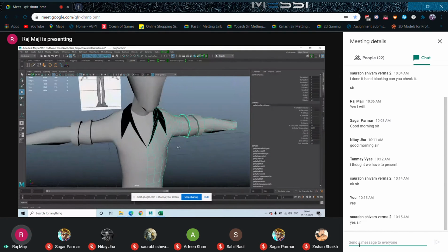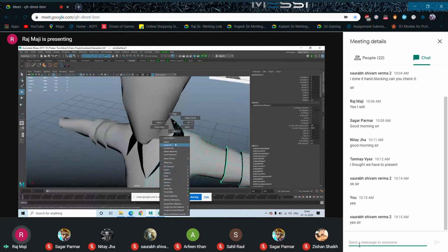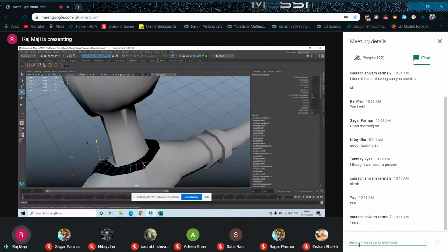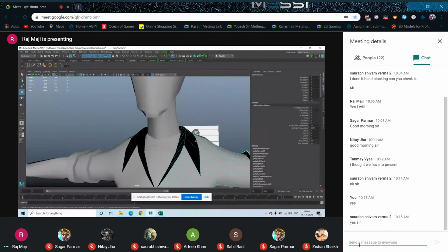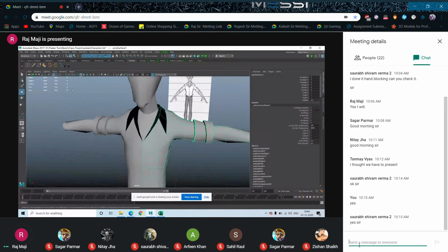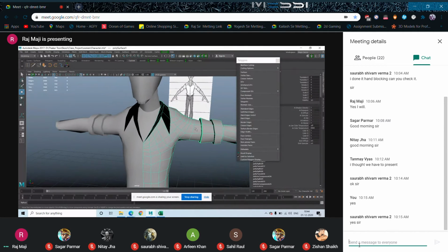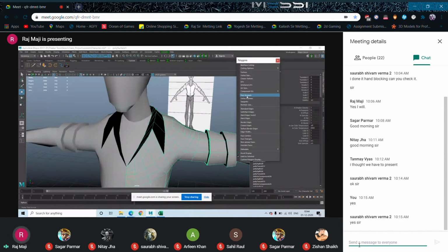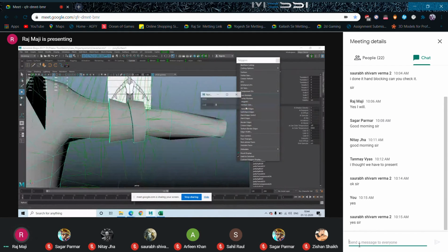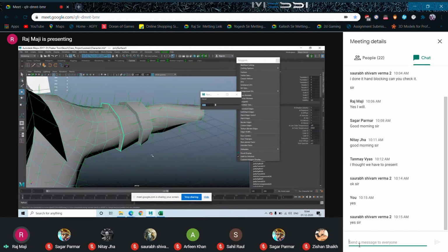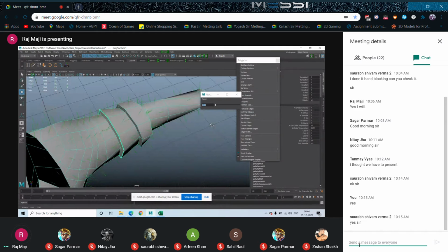Okay. But the collar is looking black in color. So for that, what can be done? Why is it looking black? Because the normal, better not to explain but to show you. So going to display polygon. Okay, over here there is one option called face normal. We all know what normal is, right? So normal size, let's reduce it to 0.1. So each and every face has a perpendicular line. So that is the normal of that face.